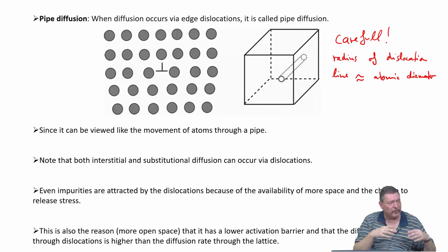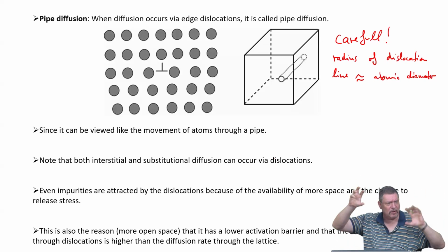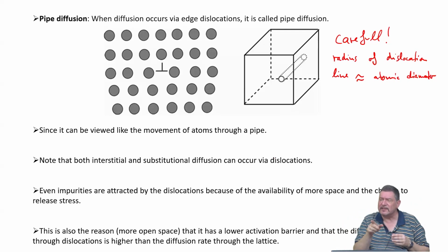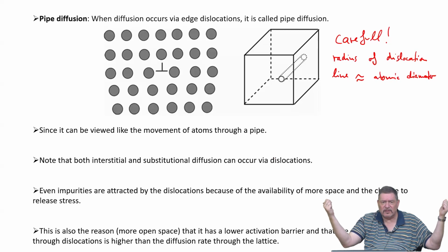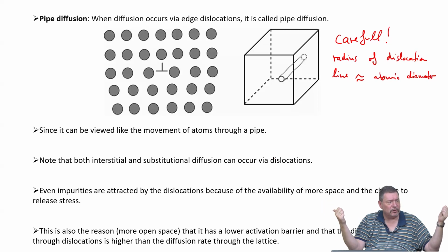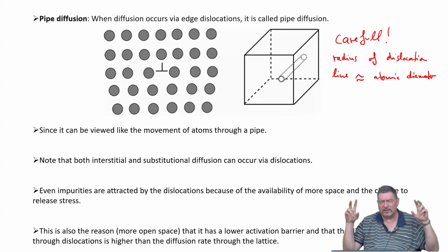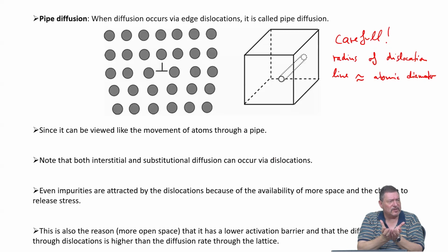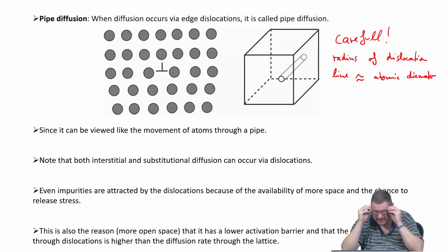So if we now think of the description of diffusion as being based on Brownian motion, on random jumps in all directions that are possible, it's not the case here, right? Because the forward jump or backward jump along the dislocation pipe will be easier than outside, because there is higher density, less available space for doing the diffusive jump. And this is causing so-called ballistic effects, because the configuration space of possible jumps is confined in a one-dimensional way. And then the mathematics again changes a bit.